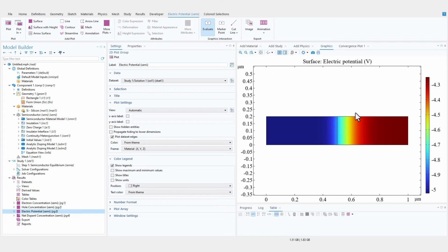And then we have this electric potential profile. Now don't worry about this -5 to 4.3. You can think of them as the extreme limits. So if you subtract, you'll see that the difference is around 0.7 volt, right? That is what we generally expect for silicon.